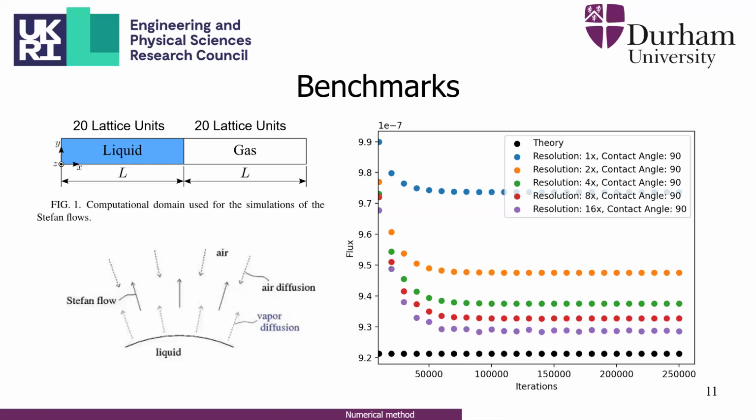That gives a boundary condition for the humidity, and there's an expression to relate that to real parameters. The other end, we just use a Dirichlet condition, but we're looking at tests with convective flow, where you can allow the vapor to come off the interface and leave from another boundary. But it basically comes from assuming the concentration on the interface is the saturation value.